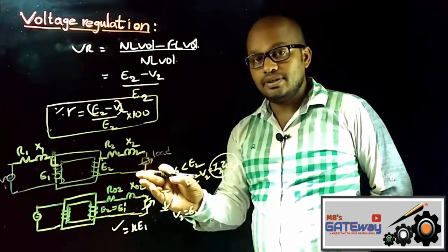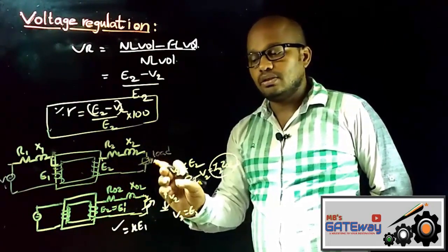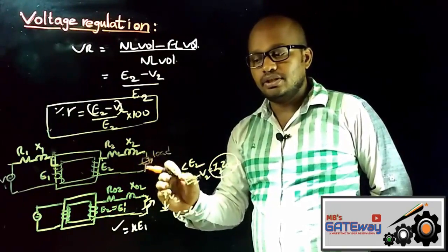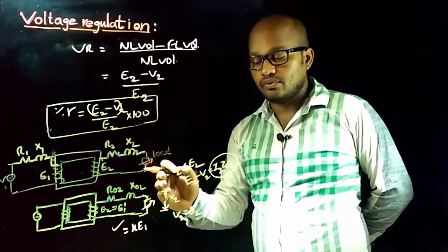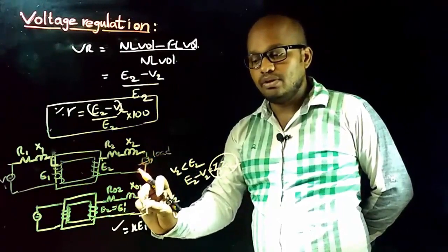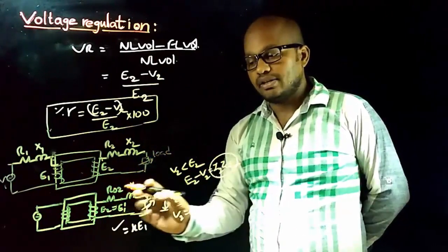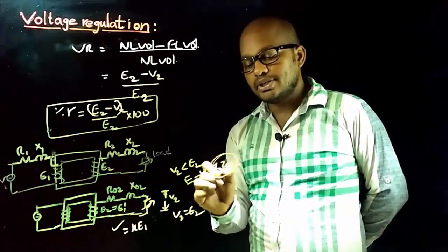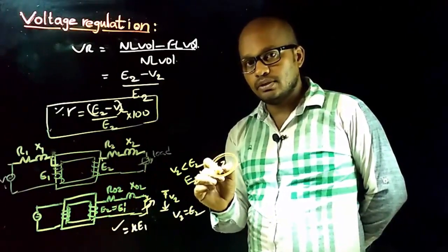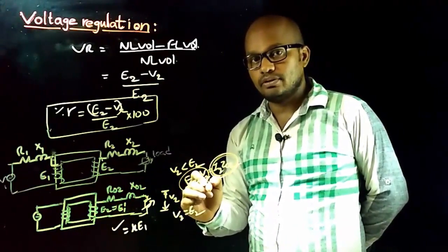So here comes the restriction of load on the transformer. The load can be increased only until a particular value of terminal voltage, and beyond that value of load, the terminal voltage available from the transformer terminals is not sufficient for these loads. From this discussion, you must understand that we require this impedance drop, that is, this difference, to be as minimum as possible.